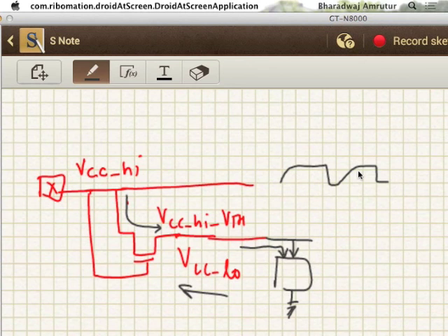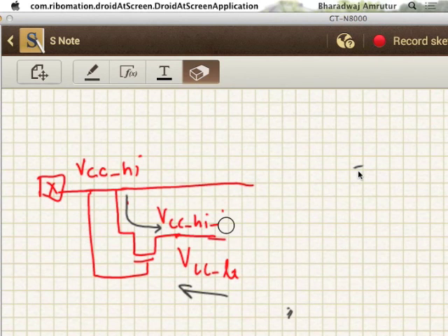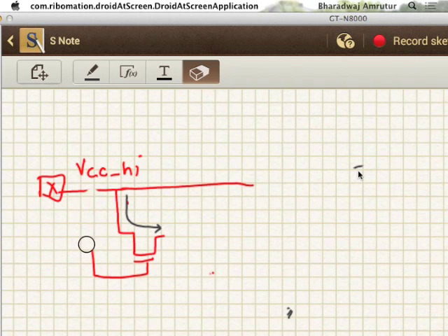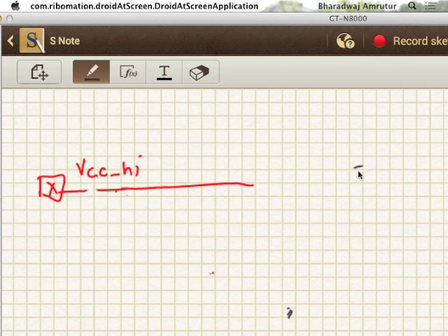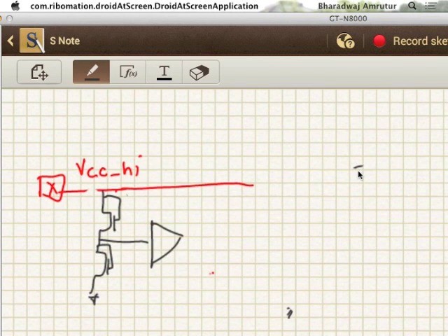But you could use this to give a reference. For example, people who are doing an analog circuits class would be able to think of a solution, but let's see if we can do something here. This gives me a reference, but then you need a little circuitry which will do the buffering and drive it, a low impedance thing. So you can use something like this to give you a reference and then drive.